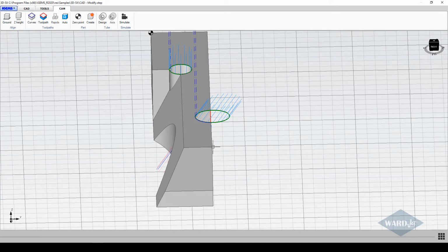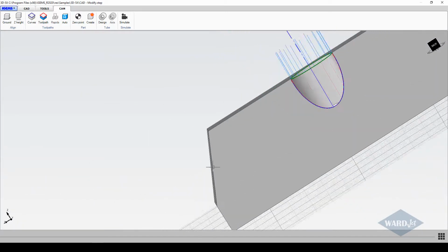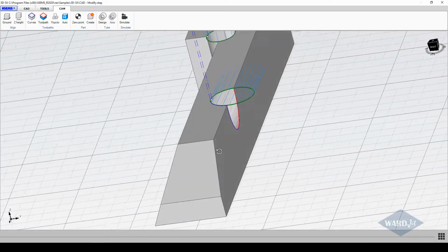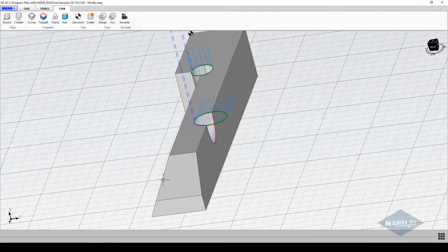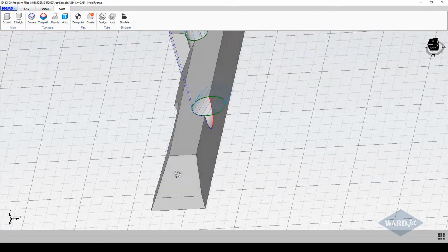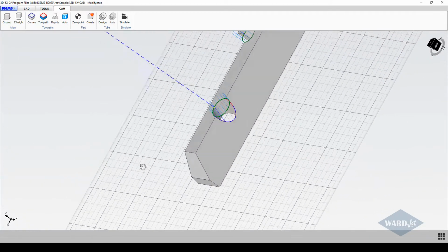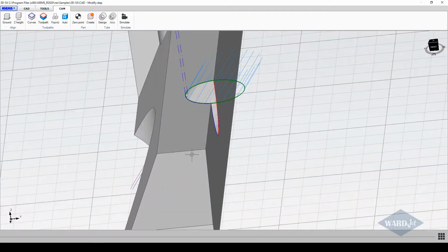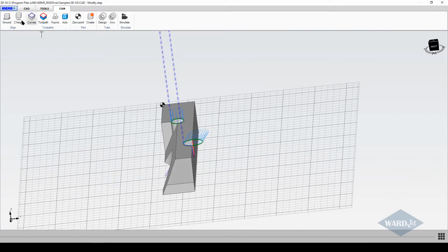What you'll get is the cutting head will start at one angle, and then as it's going through here, it's going to change the angle, because when it starts, it'll look from here to here to give it basically the angle here, and then as it's going along, it's going to start tilting over at whatever angle this face is till it's at the end here and it's pointing out this way. If your cutting head is perfectly calibrated, that might be fine, but a lot of times if your head isn't in perfect calibration, you'll see a little bit of a deviation at the top or the bottom. And if you did this at a fixed angle, if your head isn't perfectly calibrated, it's not going to be quite as visible. So I'll show you a couple ways of doing it.